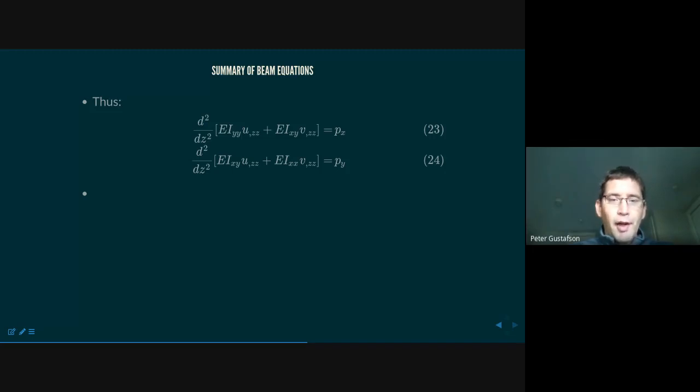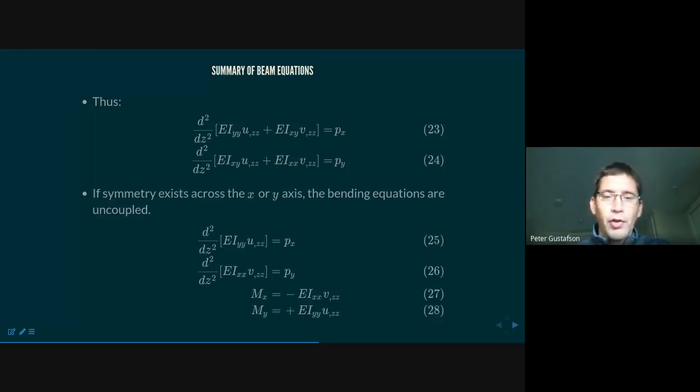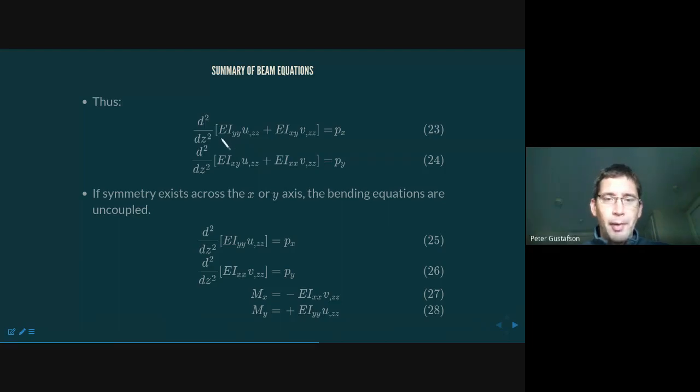Okay, so picking up where we left off last time, we had developed the beam theory equations, which are now shown here on the screen. The important concept here is that the equations are actually relatively simple. They have within them some features that we need to pay attention to. First of all, we have the material. It shows up as a Young's modulus here in the equations. We have the geometry. Now that shows up in a couple of places, IXX, IYY, and